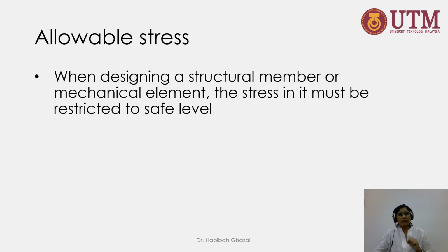And if I want to design a shaft using this mild steel, I cannot apply a torque to this material that will cause stress to generate up to this yield point. I need to have a lower allowable stress. So you need to have a factor of safety.